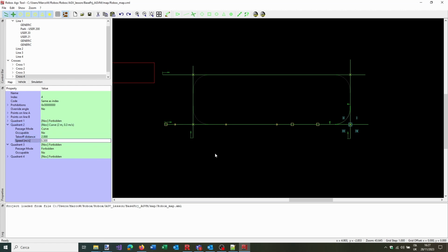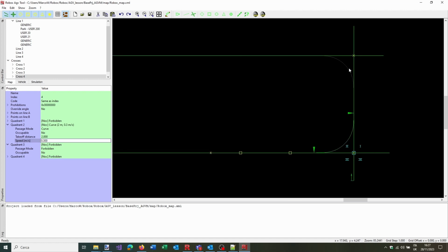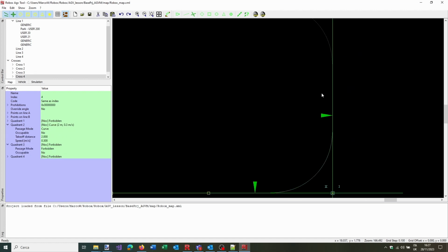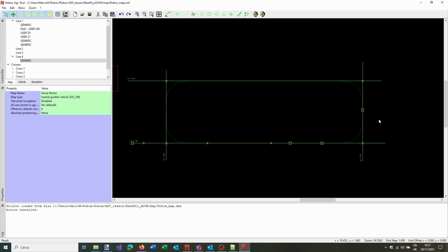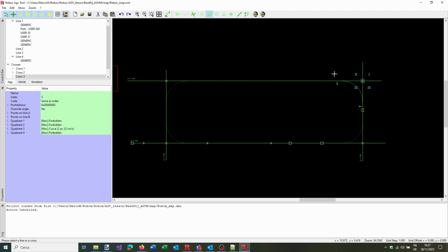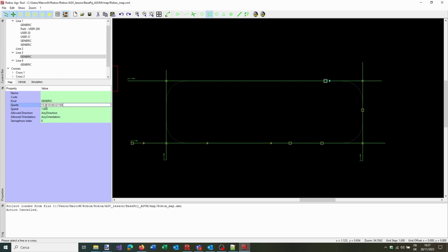If possible, longer radius curves will make it easier for AGVs to move. Now here, between these two curves, we would like to add another generic point. Okay, let's take out these pointless numbers and let's put it here. This point will be very useful for the AGV to brake its motion while it's reserving the path. In the same way, after the curve, we can just put another point here, at 15.5 meters.